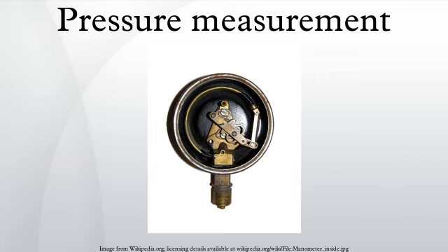Hot cathode. A hot cathode ionization gauge is composed mainly of three electrodes acting together as a triode, wherein the cathode is the filament. The three electrodes are a collector or plate, a filament, and a grid. The collector current is measured in picoamps by an electrometer. The filament voltage to ground is usually at a potential of 30 volts, while the grid voltage is at 180 to 210 volts DC, unless there is an optional electron bombardment feature, by heating the grid, which may have a high potential of approximately 565 volts.